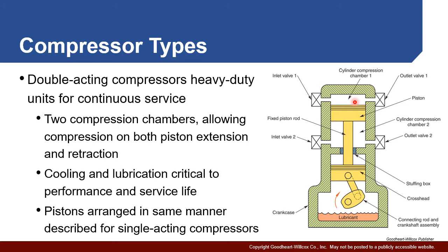Now, this is going to double your flow rate, but it's also going to double your amount of work. And of course, it's going to be a somewhat more complex system because you have twice as many things going on. The other thing about it is you're using more energy in a relatively small space, so you're going to have issues with heating. You're also going to have issues with wear and lubrication. So generally, you're rarely going to see these double-acting compressors outside. And the only place you're going to see them is really in big heavy-duty industrial situations where you want it to be in continuous service and get the most energy for your buck.